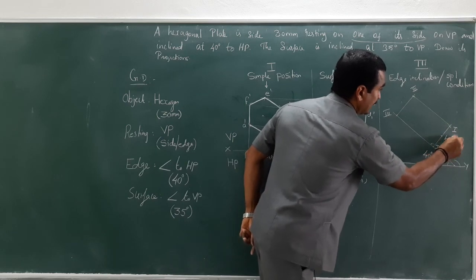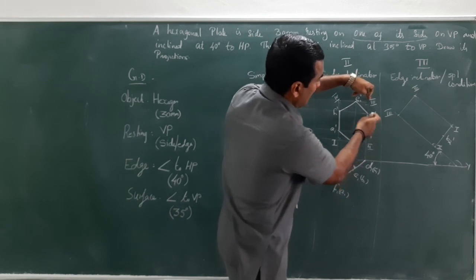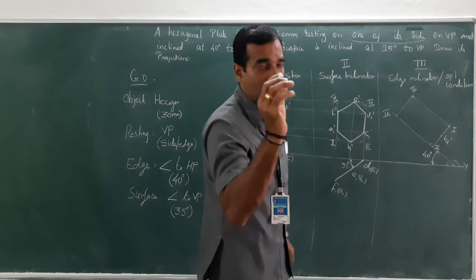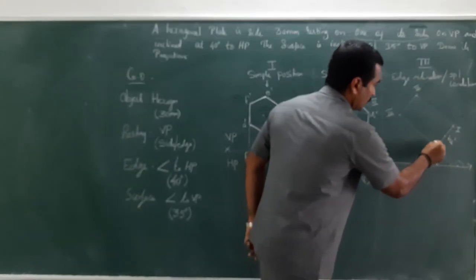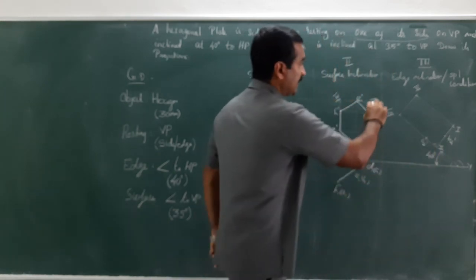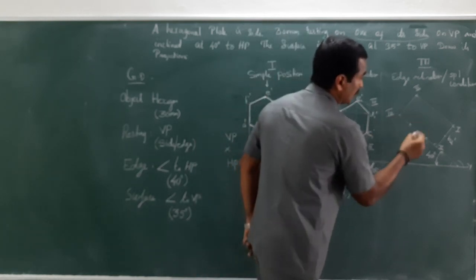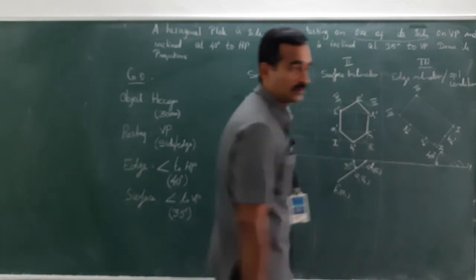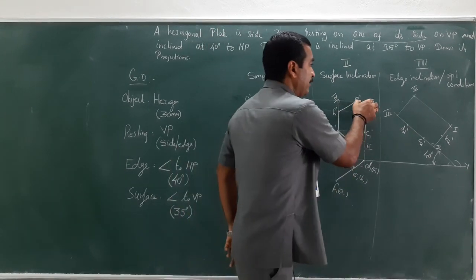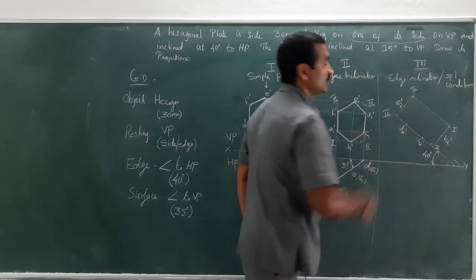This is B2 dash. Then between 2 and 3, I have C1 dash and D1 dash. Now, measure it from 2 to C in the compass. From 2, cut an arc, which is C2 dash. Now, measure it from 3 to D, and from 3, cut an arc. This becomes D2 dash. Now, between 3 and 4, E1 dash is there. From 3, I am measuring 3 to E. This becomes E2 dash.